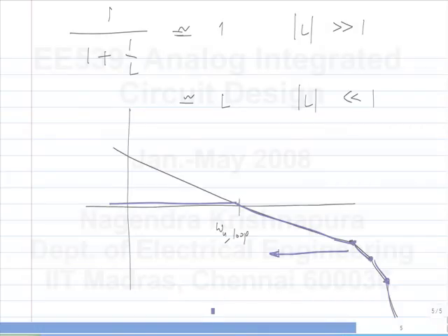Now the real answer can be found only by looking at the poles, but that may be difficult because we may not be able to find the parasitics, the analysis may be too complicated and so on. And with the simulator, it's much easier to put in sinusoids and see the steady state response, not so easy to calculate the poles. Okay.